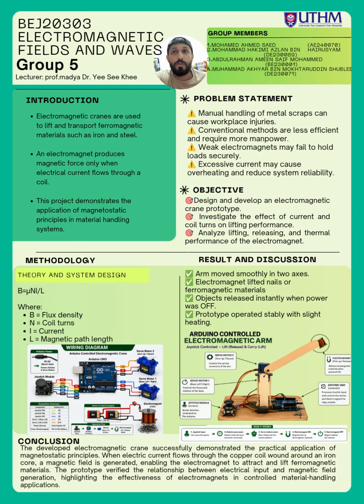The operation flow begins with joystick input. The Arduino processes the command, the servo motors move the crane arm, and the electromagnet performs the lifting and releasing process. The design successfully combines Arduino control, servo motor movement, and electromagnetic lifting into a practical material handling system.